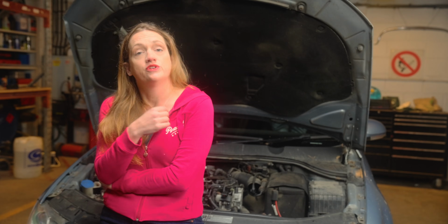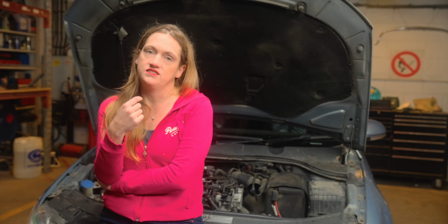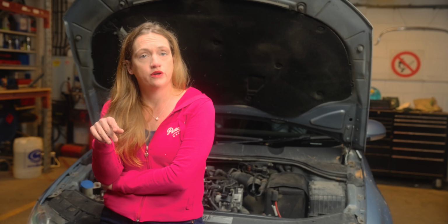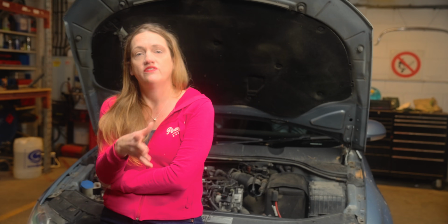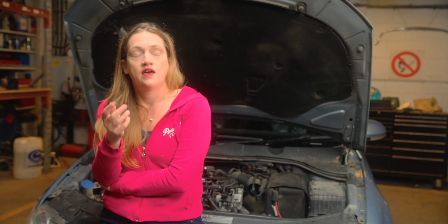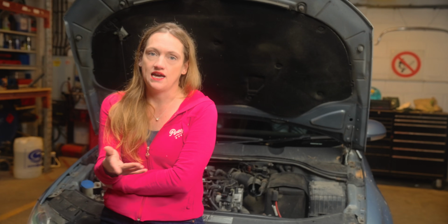That's our initial test done, which we did with the ignition off. What it showed us was that the wiring and the ECU are probably okay. The 3 static readings that we had are the circuits going through the ECU components and to earth. The ones we had that were moving around could have indicated damaged wiring. However, the most likely to be damaged bit of wiring right at the end seems to be fine.